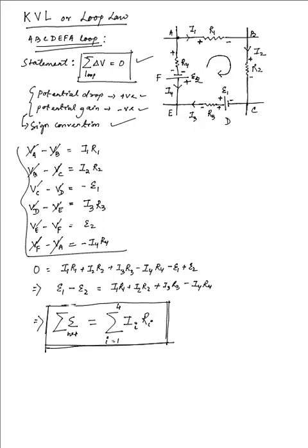In Kirchhoff's current law we had two statements as well, and here in the KVL we have two statements as well. There in KCL we had the junction law, which stated that the net current associated with a junction is zero, and here, as we consider the loop law, the net potential difference across a loop is equal to zero. The loops are always closed, obviously.